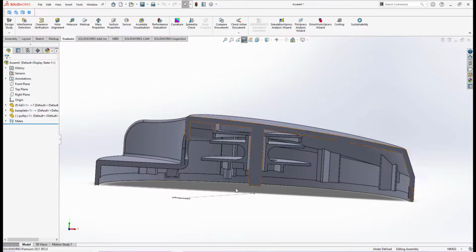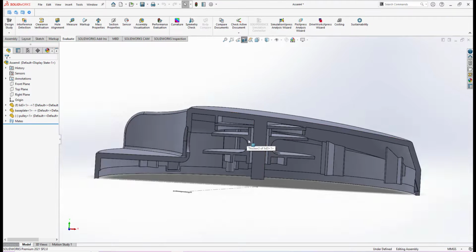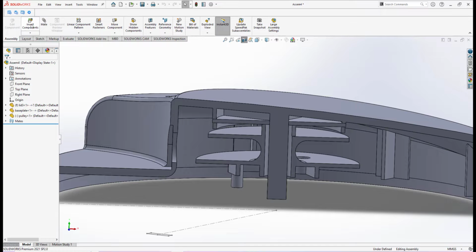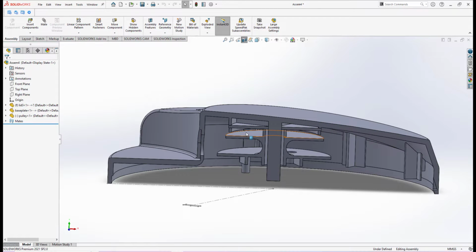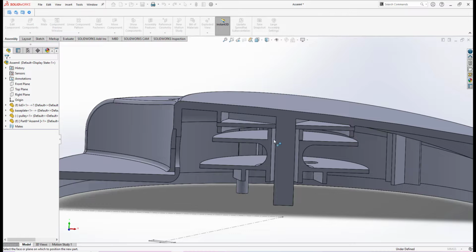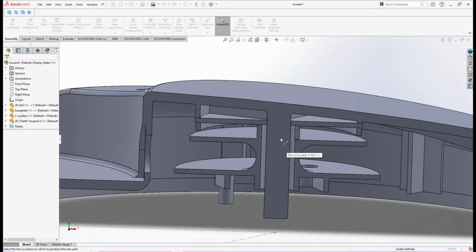Alright, okay, as I mentioned to you, I do this part modeling of my coil spring in assembly mode. If you look here, under assembly, normally when we insert a component, it means we insert all the parts that we have already done, like for example this base plate and this pulley. But in my case, I do not insert a component. If you look here under insert component, the second option is new part. It means that I insert a new part to do modeling. So if you look in the list here, we have part 8, so it means I am inserting a new part modeling into this sub-assembly.